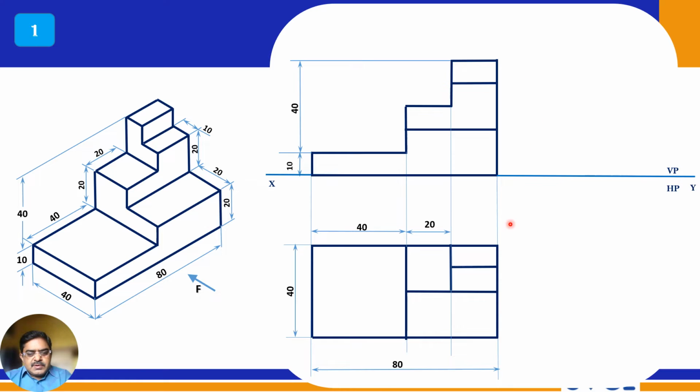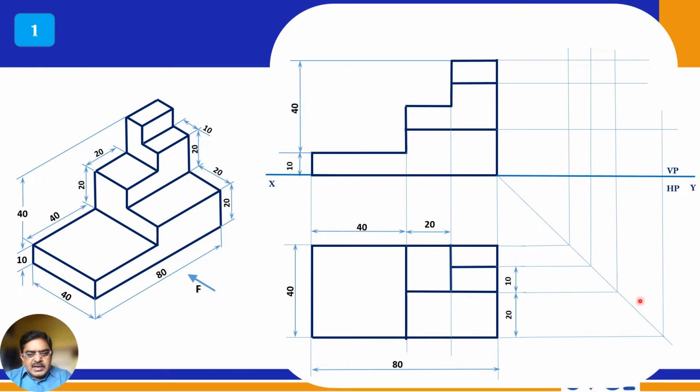Now draw the x1 y1 line, and from there you draw the 45-degree line, right? So this is the 45-degree line. So 20 mm, 10 mm, all dimensions are given here. Now from this 45-degree line you project to the top. So this is the width of 40 mm, and now it is the side view, right?